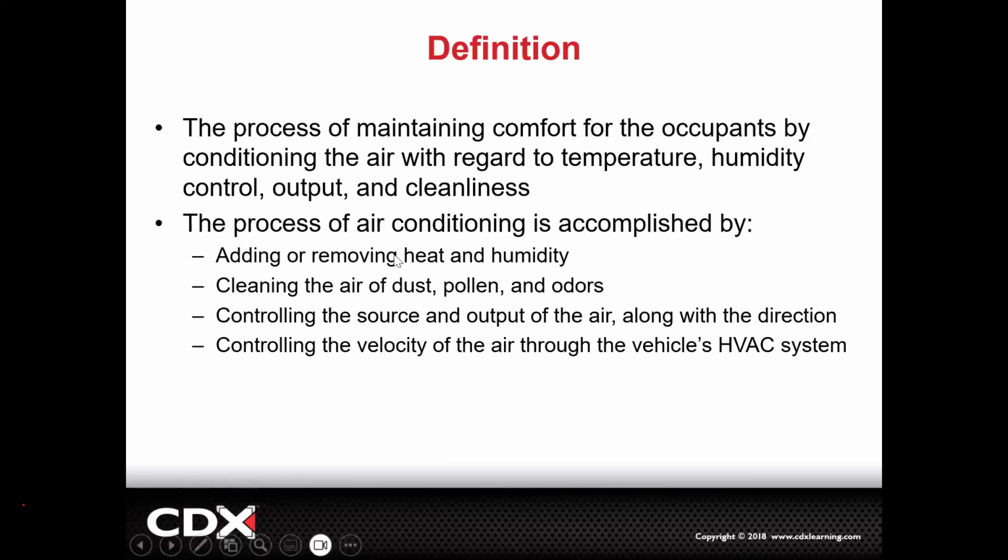Adding or removing heat, let's just start with that. If you want heat, where does the heat come from? What do you think? Probably going to come from the engine, right? From the hot coolant, would you say? What if you want to remove heat? How are we going to do that? Goes through the condenser. Yeah, exactly. We're going to use the whole AC system, compressor, condenser, evaporator, all that. Yep. And both of those remove humidity. So that's what's kind of interesting.